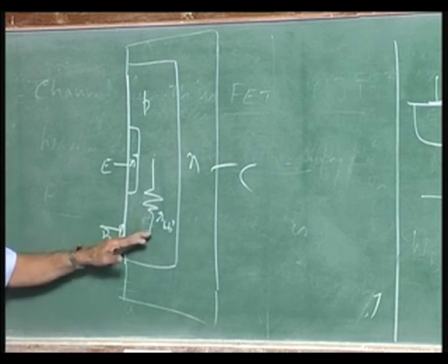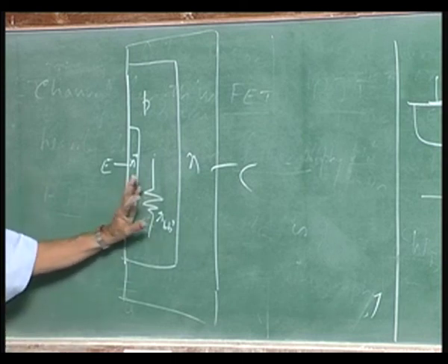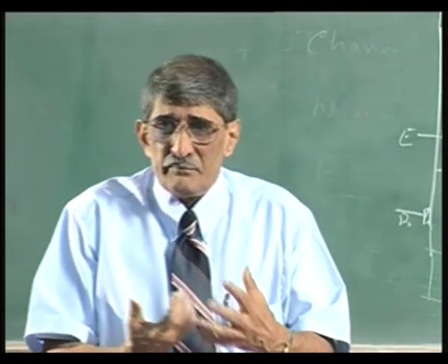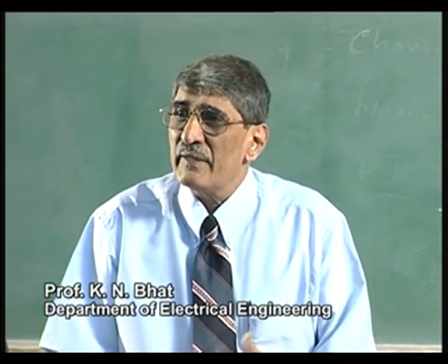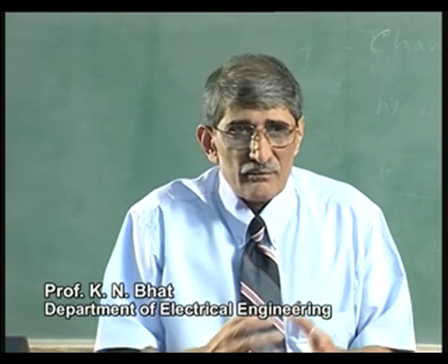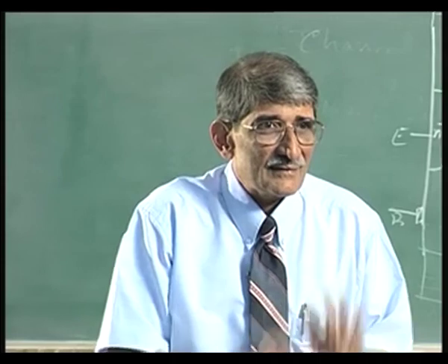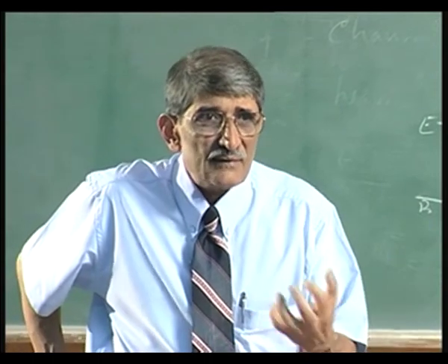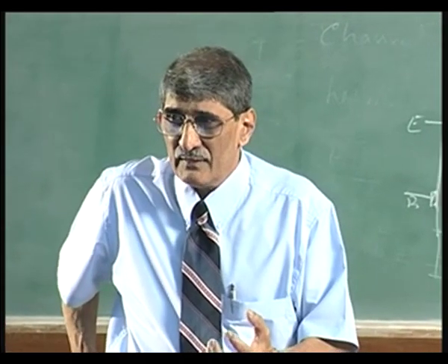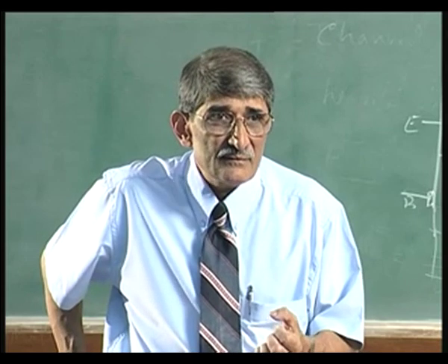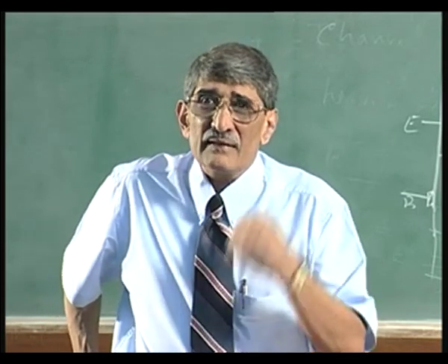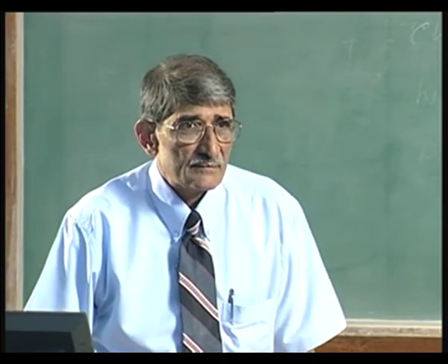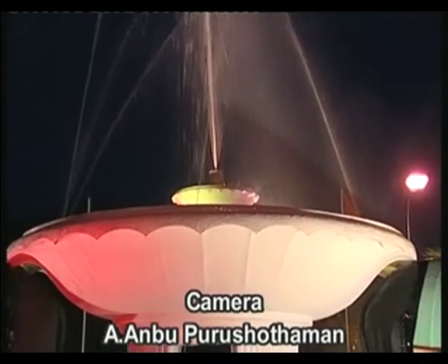So, that increases. So, what we will have to do is think of ways of reducing RBB dash, the base resistance. That can be done by increasing doping. So, it goes without saying, whenever you have reduction in thickness, you must increase the doping. Now, if you increase the doping in the base, what are the effects which follow? It has tremendous detrimental effects if you increase the doping, but without increasing doping, you can get better performance by moving on to HBT. I will discuss some of these aspects next lecture.